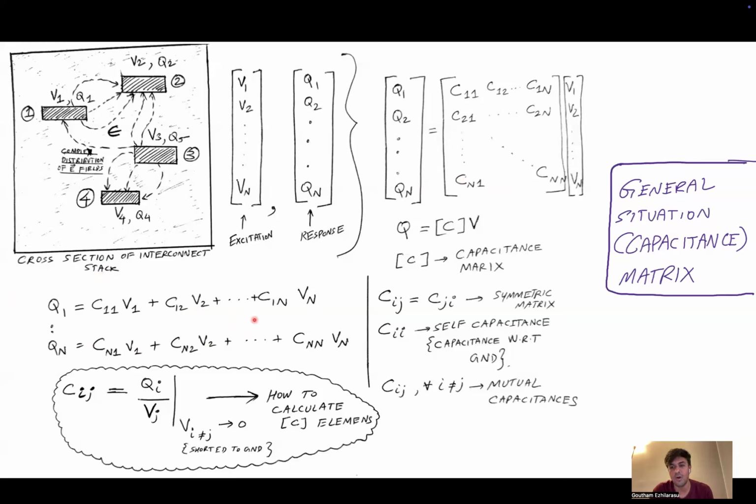So you can see how in a multi-signal network, you have to consider the various mutual capacitances, and then consider what signal transitions are occurring, what the amount of coupling from the different aggressors to the victims is, and then design your network or your links so that you can minimize this cross coupling.